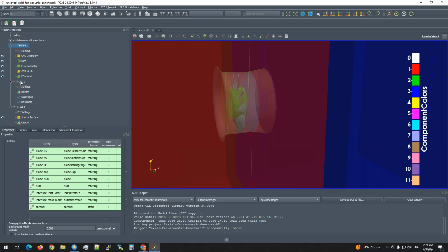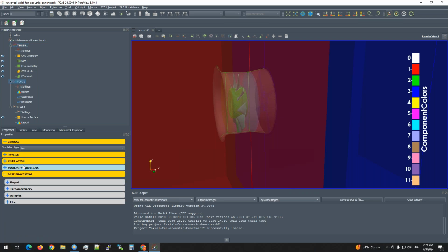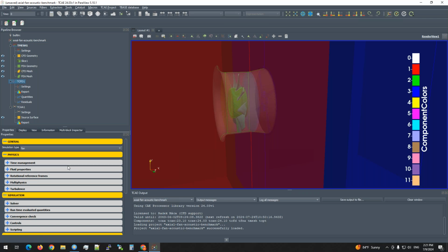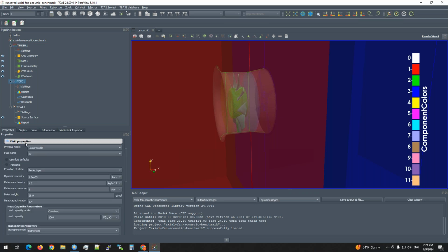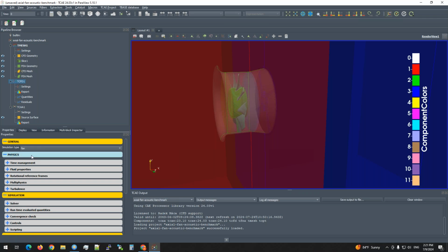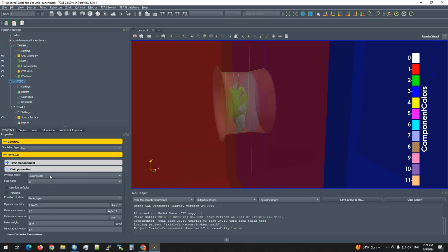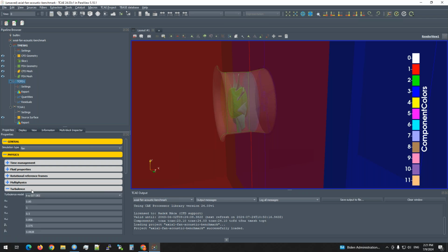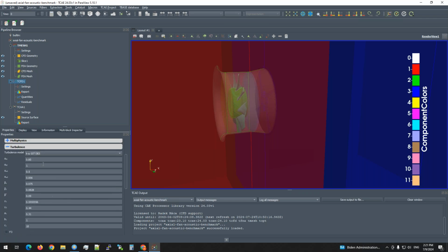So this is the meshing. For the CFD simulation, you set it as a standard CFD simulation, so standard fluid properties. We need to have it compressible to include all the effects, the physics which influence the acoustics. For the turbulence, we typically go for some hybrid models, some kind of DES models.